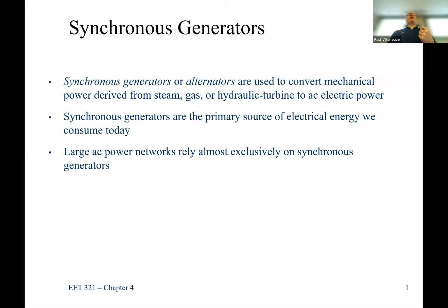that almost all the generation for many years was synchronous machines. If you remember when we determined the speed of operation of the Northfield Mountain hydroelectric facility, we said there were 48 poles, I believe. So that's a 48 pole generator. That's the number of poles on the stator and on the rotor. But the rotor itself uses what's called a synchronous machine design. And we'll get into what a synchronous generator is.